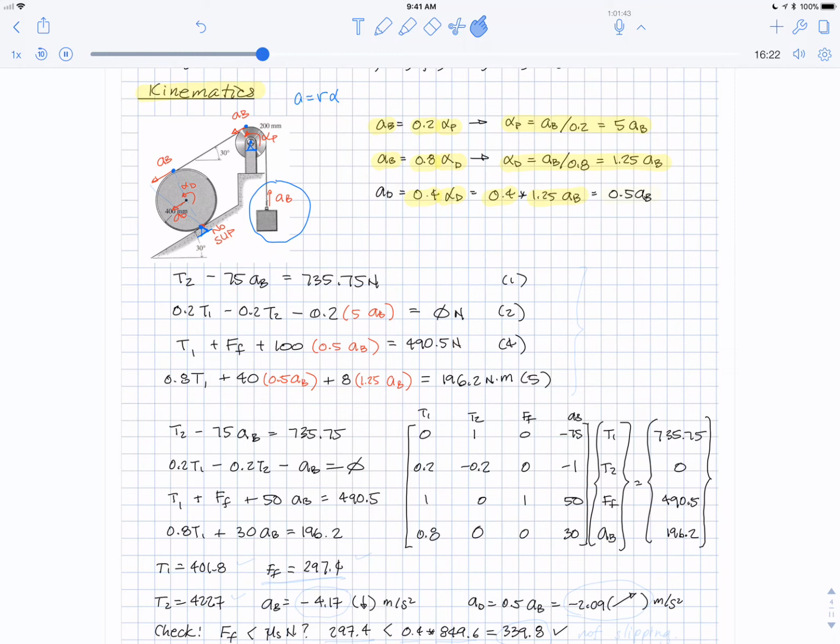Multiply it all out and you get half of a block. This makes sense: if your acceleration is proportional to your distance from the pin at the bottom, the middle of the disc is half the distance away as the top of the disc, so that's half the acceleration.